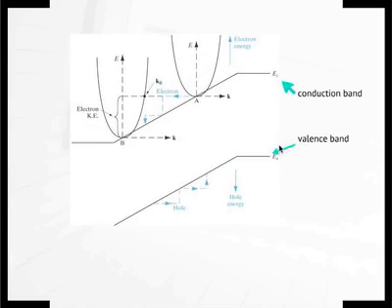Okay, so another way to look at these things is by looking at the band diagram, applying electric field and looking at currents, I mean. Remember, we can look at band diagrams in two ways. We can draw the simplified band diagram, which is basically a straight line, and imagine a valence band and a conduction band.